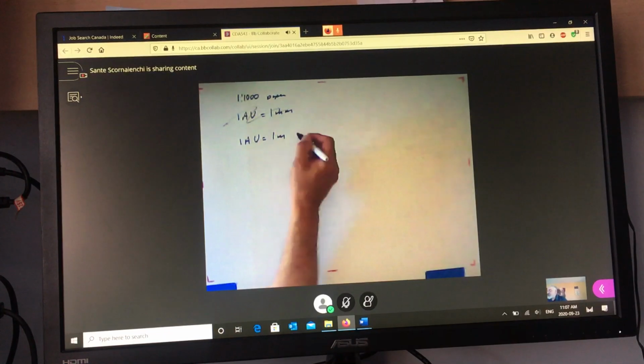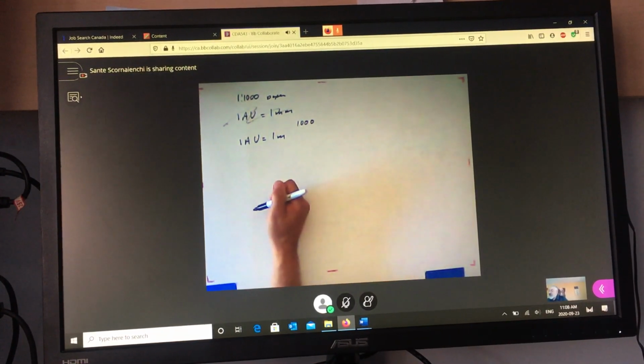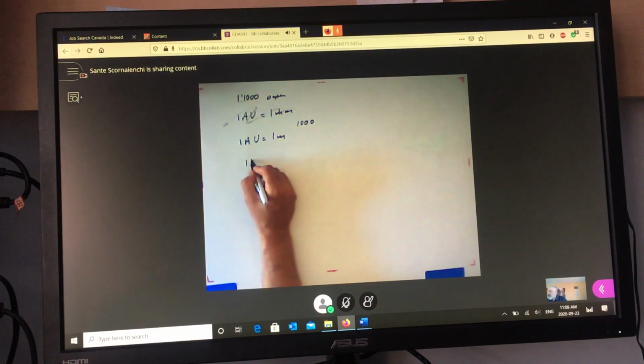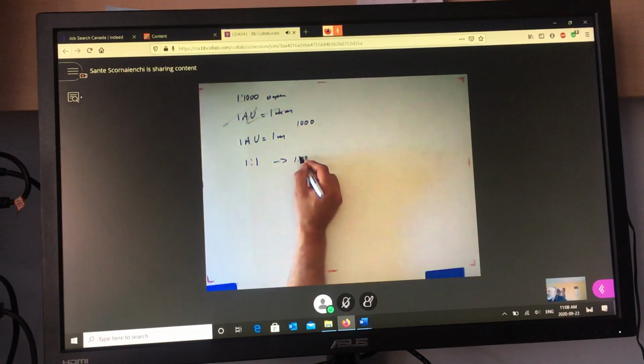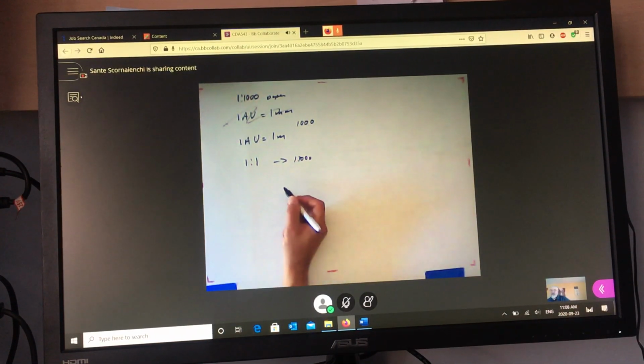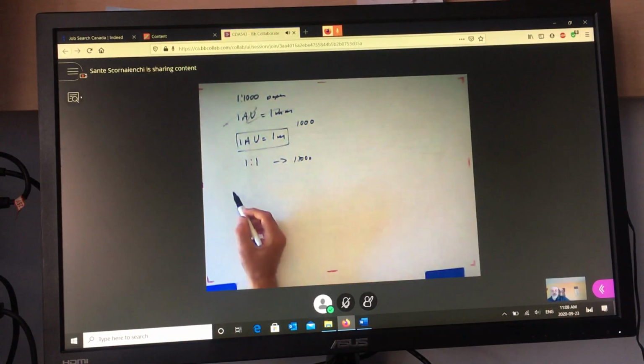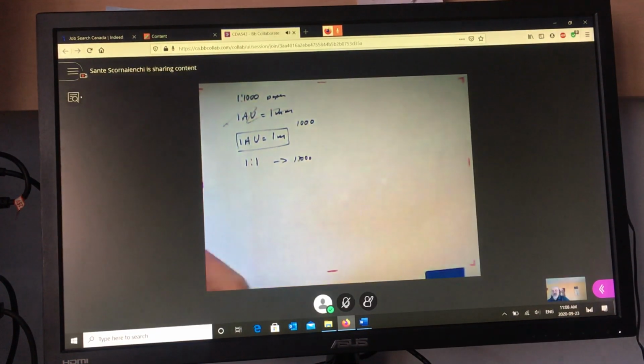There's a factor of 1,000 at play. So if I want something to plot on paper at 1 to 1,000, I have to divide the 1,000 by 1,000, right? So my plotting scale is 1 to 1. And then on paper, that translates into 1 to 1,000. Okay? The general rule is whatever scale you want, you have to divide by 1,000 if you're drawing in meters, which we will be. Everything we draw is in meters, not millimeters. Okay? But if you were an architect, we wouldn't be having this discussion. But because we're civil practitioners, we're doing something else.